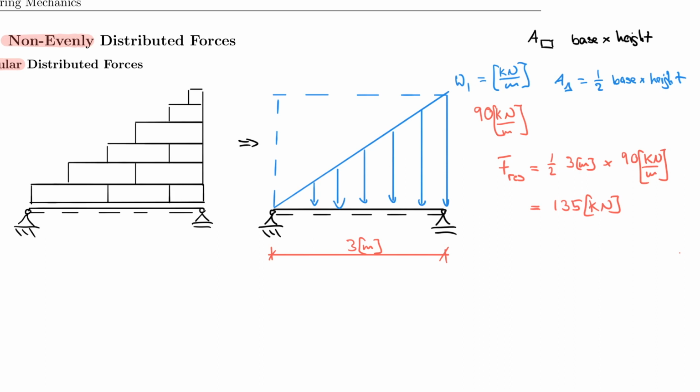What you don't know is where it acts. Well, actually you do know, but to be clear here, I want to make sure that everybody is on the same page. And so I want to explain that anyways, even if you already know. Remember that when we had a rectangle where the force was lumped, it was right along the diagonal, right? And where the two diagonals met. Now for a triangle, I can do something very similar. I can not draw diagonals, but I can find the midpoint and connect it to the vertex on the other side. So I can do that here.